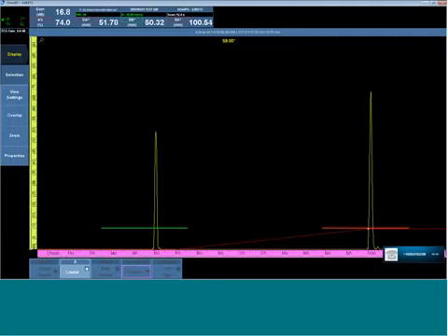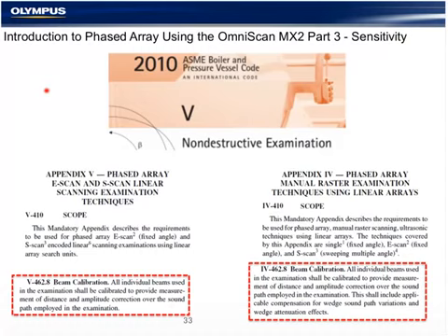Our codes and procedures are very clear about inspection sensitivity. It's directly related to the reject rate that was designed by the code. Little holes produce a very sensitive inspection with lots of rejects, typically, whereas big holes are a less sensitive inspection that would allow more flaws. Depending on the code, the sensitivity of the inspection could be very different. An AWS fabrication weld could have flaws that are not permitted in a closure weld for a pressure vessel or piping.